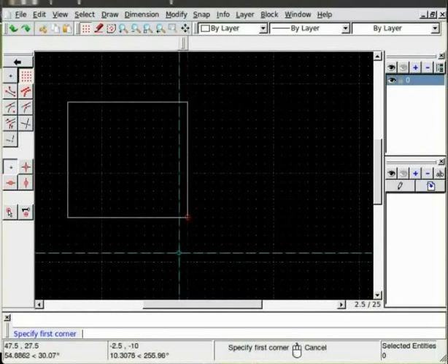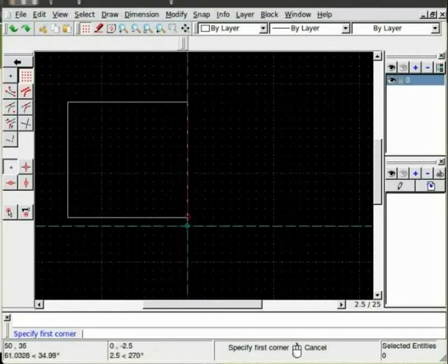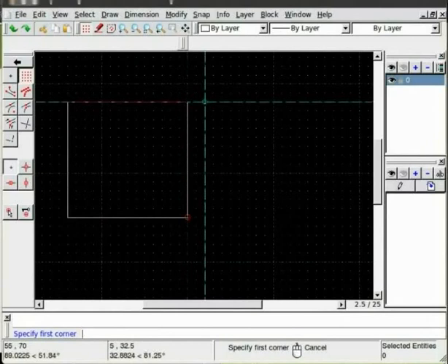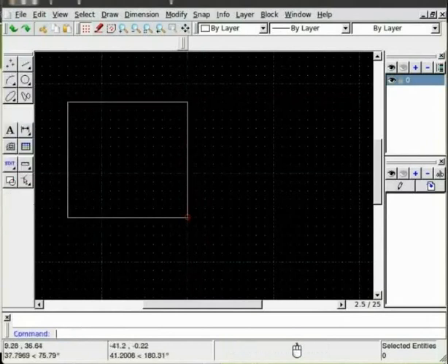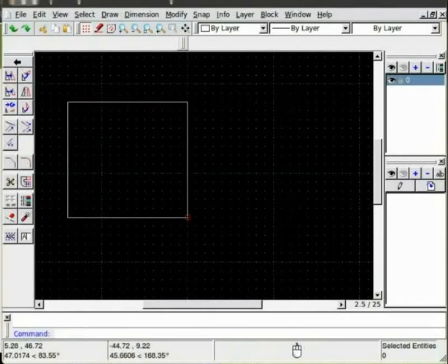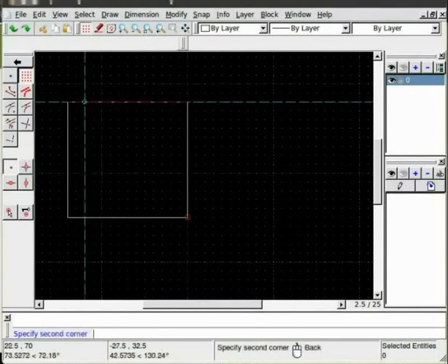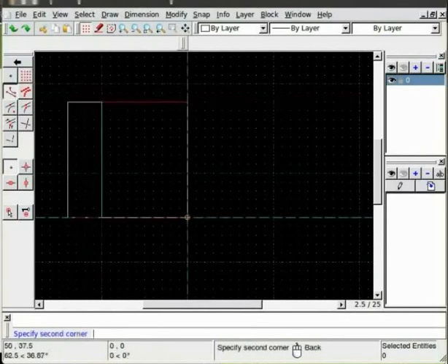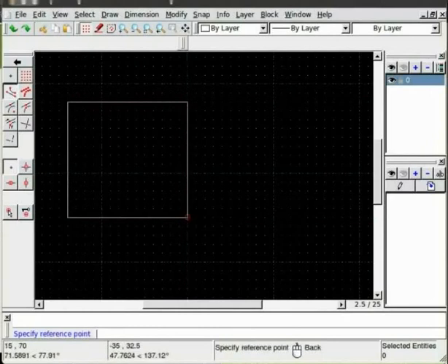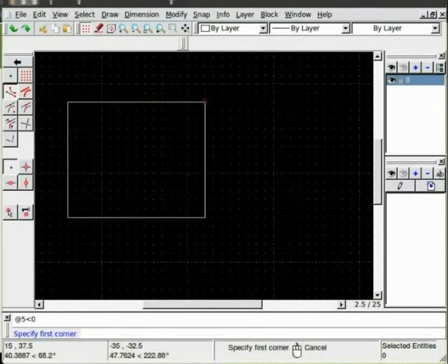You can also stretch object by specific distance. Let us stretch this rectangle on right side by 5 units. For this, select stretch icon. From snapping options, I am keeping snap to grid. Select both the corners. After the selection, give reference point. I am giving top corner. Now for target point, since I want it to move by 5 units, go to command line and type @5<0 and the rectangle will stretch in that direction.